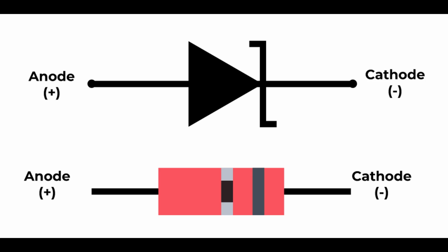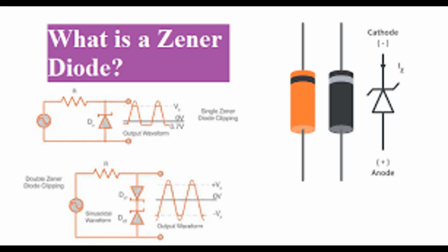Applications: clamping is useful in video signal processing, DC restoration in communication systems, and in circuits that require precise voltage levels for further processing. In both clipping and clamping, the choice of diode and the circuit configuration determine the specific characteristics and behavior of the output signal. These techniques are valuable tools for shaping and controlling signal waveforms in various electronic applications.